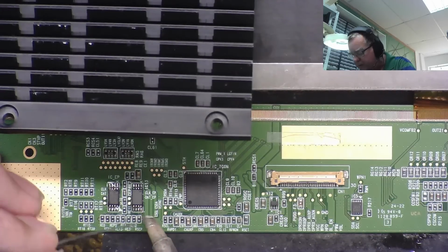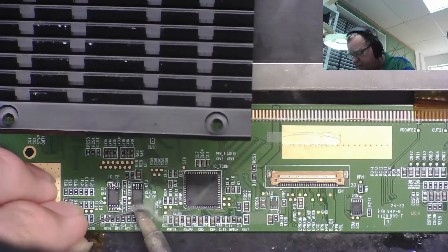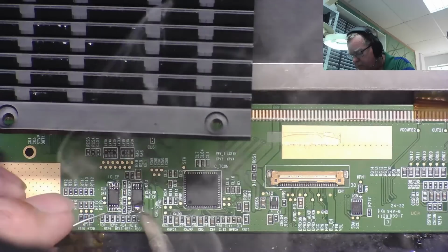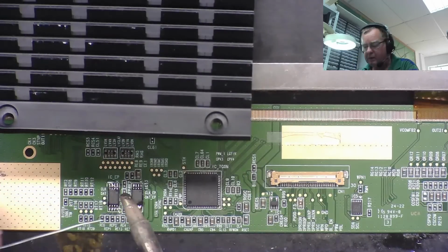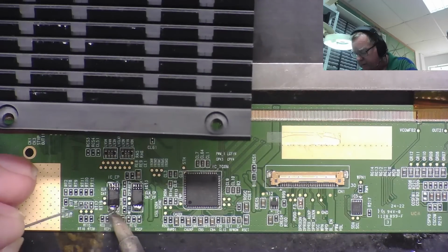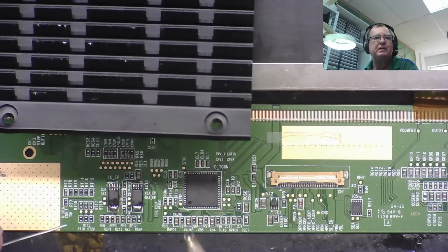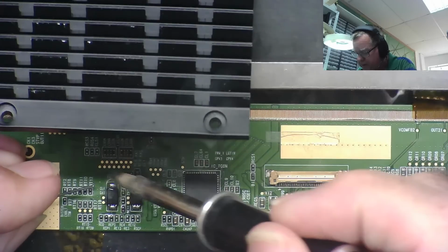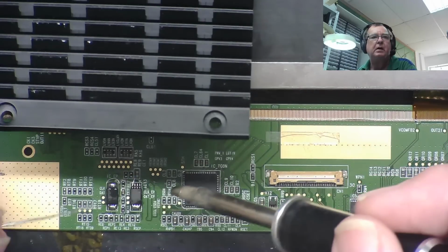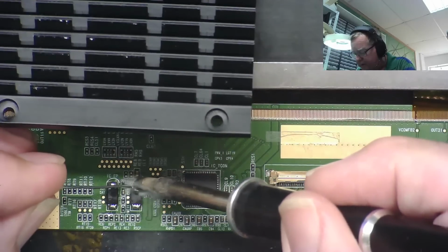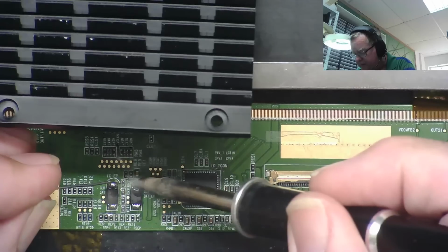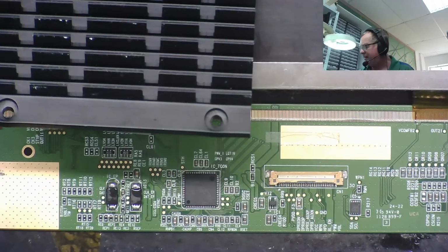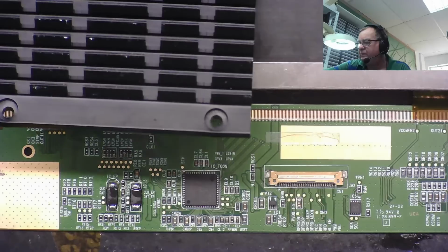I want the chips, so I want to put them onto the board. Yeah, blob of solder on there. I think if you've seen some of my other videos, you've seen me use this technique before, and this helps a lot when you're trying to desolder stuff with hot air and not disturb stuff that's nearby. As I've mentioned before, this leaded solder will form an alloy with a lead-free solder. That should melt quicker than the lead-free solder, and I should be able to get this chip off quite easily.